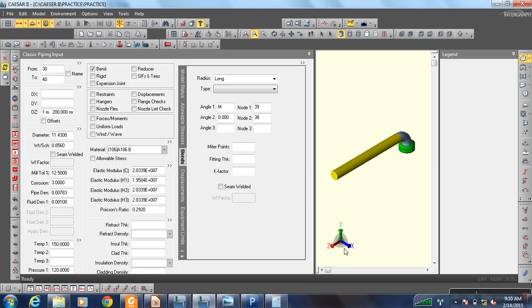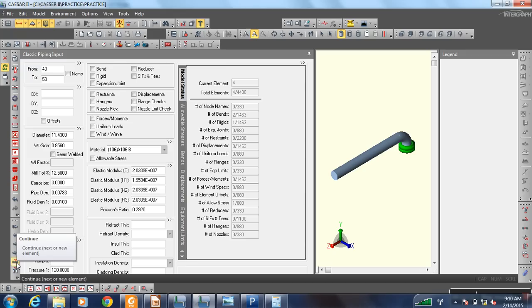That's in minus Y direction. Y is about going upside and down. So last time I did put it. Yes, save and continue. Control S is for saving this file. This Alt C is for continuing the pipe. Saving this pipe here, continue, means it won't be saved in the file, you need to save it again. Just for saving this pipe.